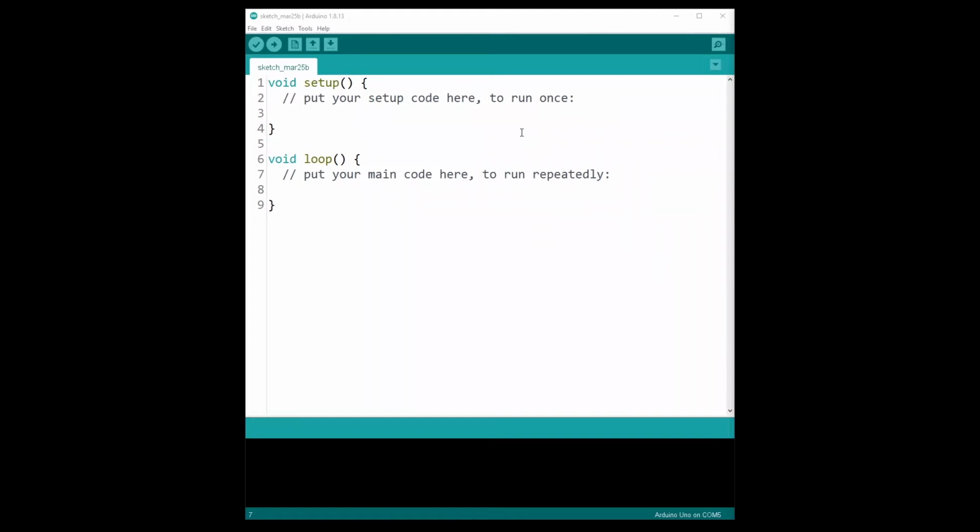So if you have already used the EEPROM memory on the Arduino board, you know that you can only store a number between 0 and 255. So you can just store 1 byte per EEPROM address. But now, what if you want to store an integer, which is actually stored on 2 bytes? What if you want to store a value that is above 255?